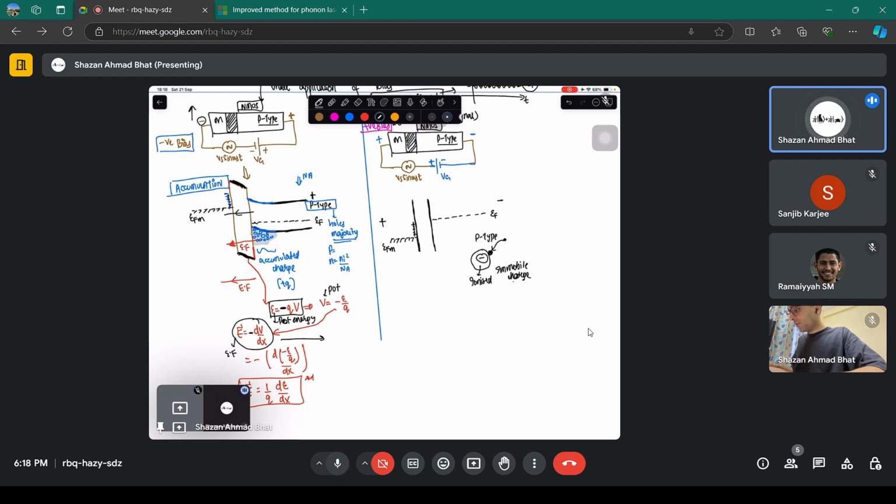That is what happens in a p-n junction also. And what are those immobile charges going to do? They are going to stay at this particular region and form a depletion region. Inside the bulk, the band will remain the same as it was earlier. There is no change in the bulk. Most of the change happens at the interface because of this particular charge at the interface. So it's like a capacitor action.